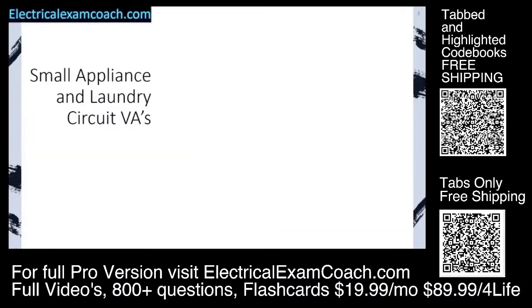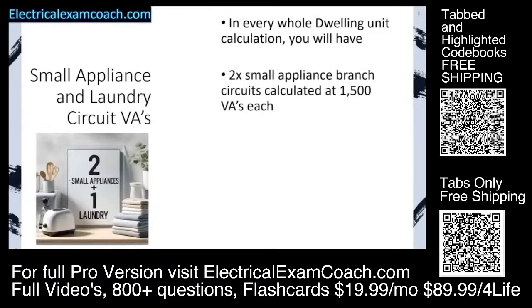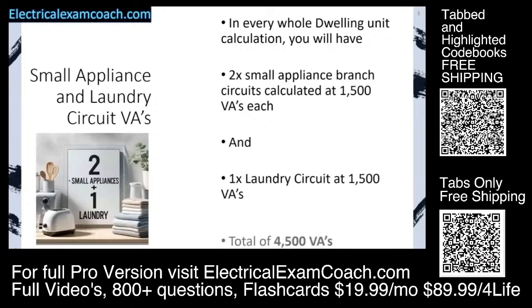Now that we've learned about our 3 VAs per square foot, now we have to learn about what's called our small appliance and laundry circuit VAs. In every whole dwelling unit calculation, we're going to have 2 small appliance branch circuits calculated at 1,500 VAs each, and 1 laundry circuit calculated at 1,500 VAs each for a total of 4,500 VAs.